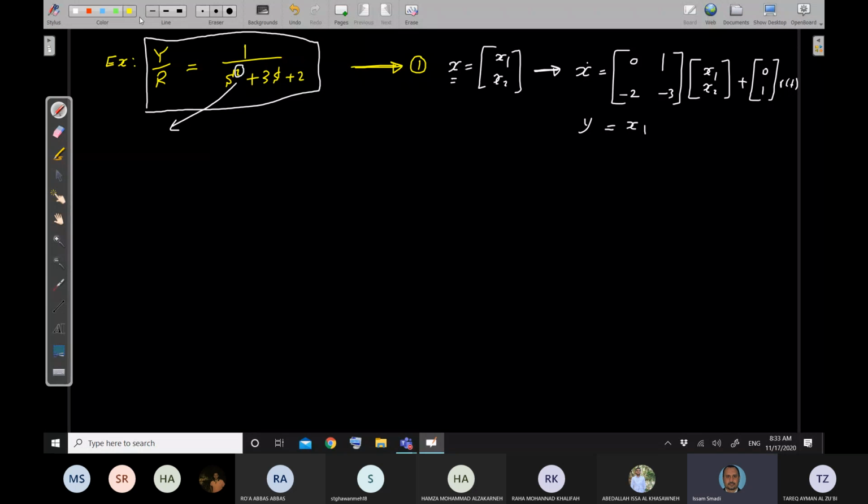Now I will redo it in detail, but let's first understand the first method and the second method. The second method states that I get the roots of the characteristic equation. So if I solve the characteristic equation s squared plus 3s plus 2 equal to 0, to find the roots, it will be (s plus 1)(s plus 2) equal to 0. So the roots are -1 and -2.